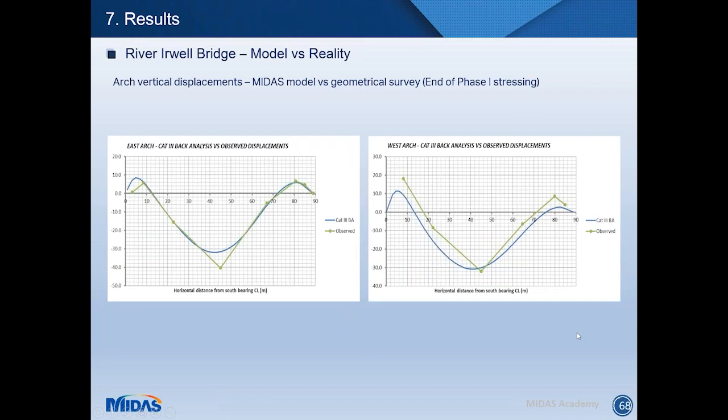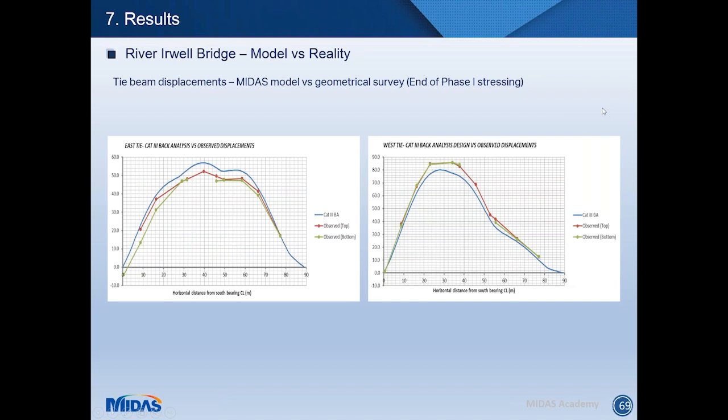And the same happened throughout the construction sequence. Obviously, this was done almost daily during construction, and models were corrected to match the right stressing level read on the hangers. And as a consequence of all of this control, a new stressing sequence was issued, produced by the designer, checked by us, the cut-through checker, and was issued to the site construction team. And this is the same at the end of phase 1 stressing.